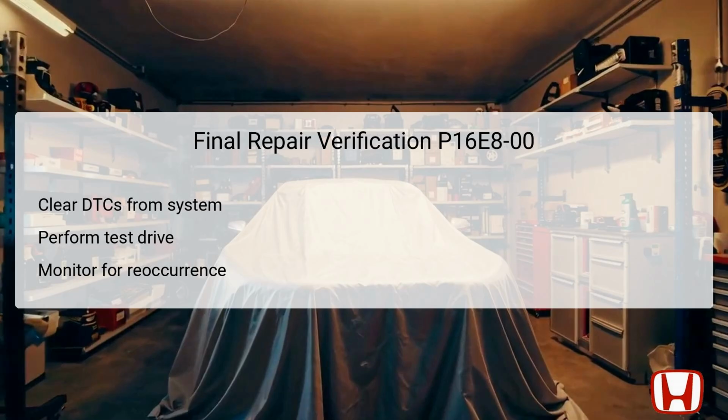This process begins by clearing all stored DTCs from the vehicle system, including the P16E8-00. Once the DTCs are cleared, a test drive should be performed to allow the PCM to run through its diagnostic checks and reevaluate the status of the shutter grille communication. During this drive, technicians should monitor the vehicle's performance closely for any signs of recurrent issues.